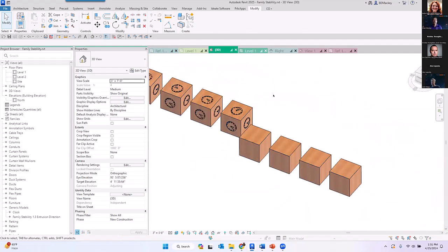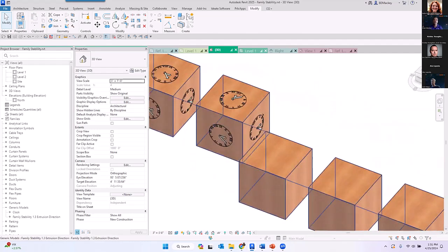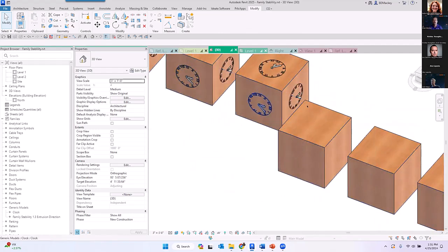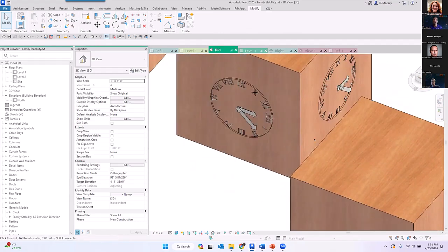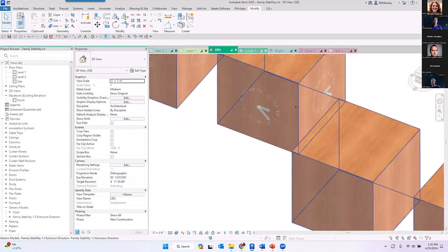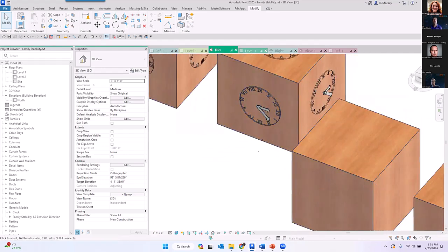Okay, so just understanding the directionality of your families can matter too. The other thing is, what if I wanted to rotate this? What if, on the sides, when I brought the material in, I don't want to have to associate a new material in Revit with a 90-degree material? I've got wood grain 90, wood grain 0. I don't want to have separate materials with separate images to start getting that into play.